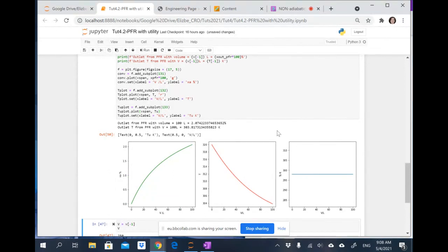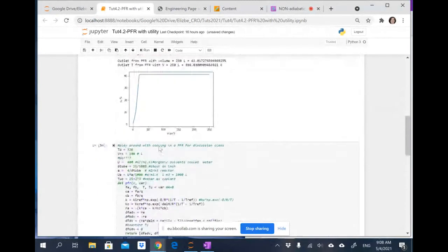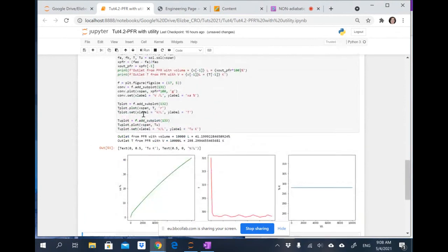So look what I have done by adding this. In a 100-liter reactor, marvelous, I can achieve an astronomical 2% conversion by cooling stuff down. So it doesn't look good for me. However, I can see what the problem is: if I consider my rate, I'm not utilizing that initial increase in the rate. This is just showing a constant decrease in the rate, but at least it's not at equilibrium yet. So let's see what happens if I really go crazy with my reactor volume. If I've got a 10,000 volume reactor, what's going to happen?